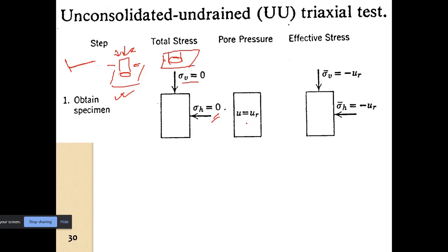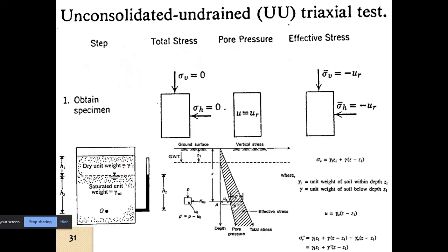Then of course the pore water pressure, while taking the sample out of the position where it was. The sample was in this place, so we drilled the hole, used an undisturbed sampling, and took out the sample. From the sampler we then took out the sample and placed it on the pedestal.